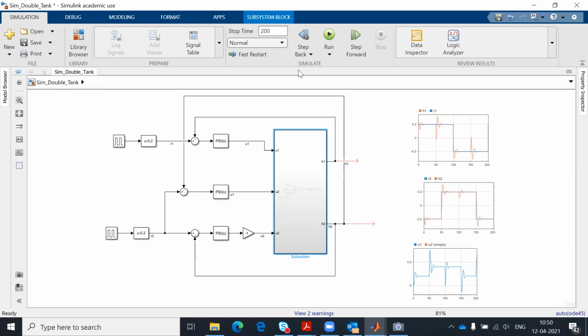In robust control, we design one controller for all working points, but we design the controller to be robust so it is conservative. It guarantees the stability in all working conditions. But as I said, the performance could be affected. What is adaptive control? Adaptive control means that you have a structure, you design a controller, but the controller is parametric.